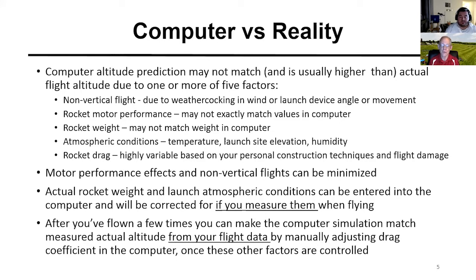So the effects of motor performance and non-vertical flights can be minimized by paying attention. I'll talk about those later. As I mentioned, you have to know the actual weight of your rocket and atmospheric conditions. And if you enter those into the computer and use that as the basis for your flight simulation, then you will get a simulation that's closer to reality.